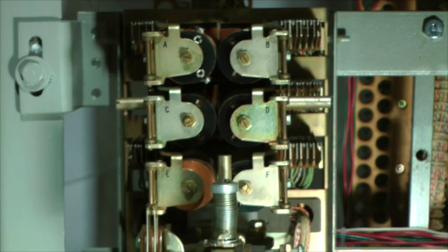It should be noted that the mechanical motions you've just seen and will be seeing throughout this video depict individual switch parts shown in sequential clips. In actual line finder operation, much of this motion occurs in unison. All parts attached to the line finder shaft move in unison. There are a number of parts attached to or directly contacted by the vertical, rotary, or release armatures. All these parts move in unison with their respective armatures.